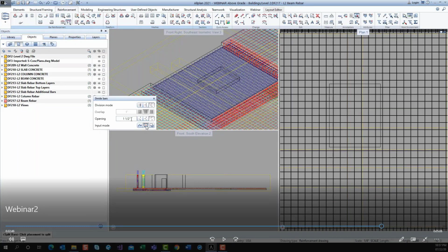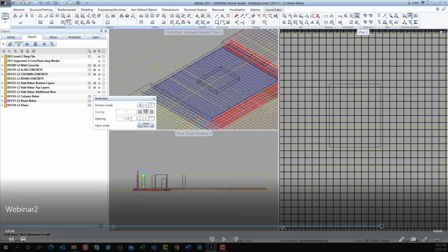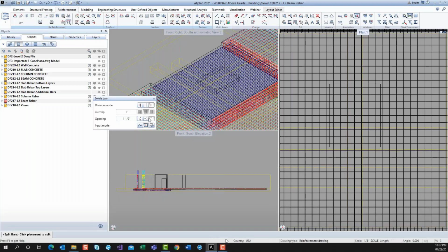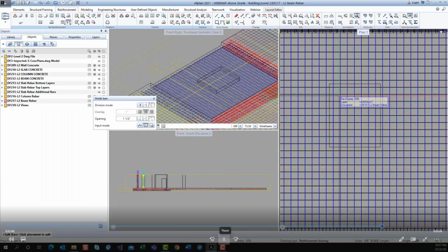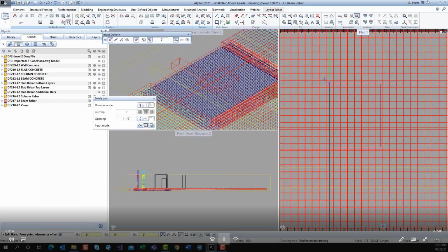And then I'm going to choose the polygon command, basically if I had the ability to select internal to an object, similar to picking island detection and so on. This time that's how I'm going to do it, and I'm going to do a 1.5 inch offset trim around that opening, so when my bars get trimmed, they have a cover. So by applying the opening, I'm going to select the bars I want to trim. I'm going to select the opposite corners of my opening,